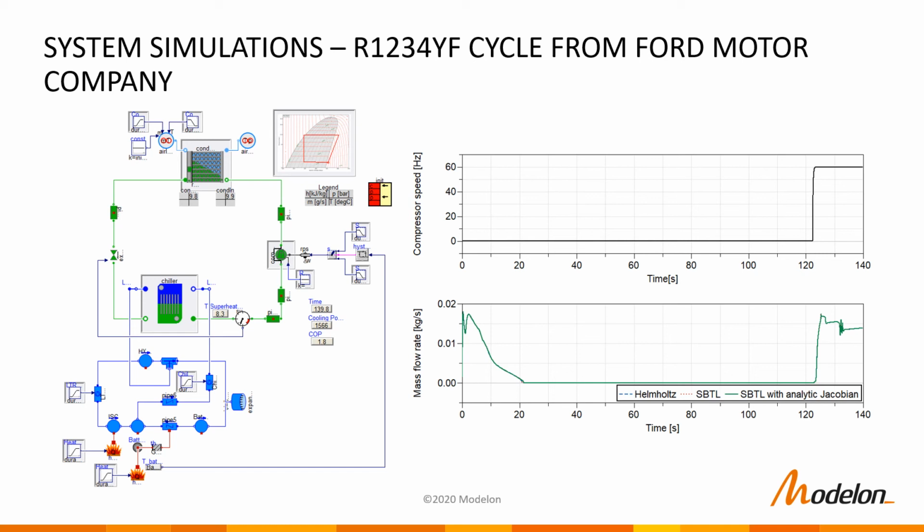Here we have a vapor compression cycle connected to a cooling loop. The system is initialized with a certain flow rate, and the compressor is immediately off at 0 seconds. At about 22 seconds, the flow rate in the chiller goes to 0. The solid mass connected to the cooling loop is experiencing a constant heat flow input, and the temperature of it keeps rising, heating the refrigerant in the chiller and creating a super tiny reverse flow. The compressor kicks in when the solid temperature exceeds a certain threshold.